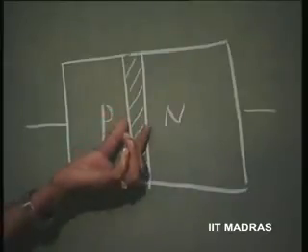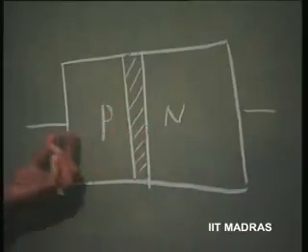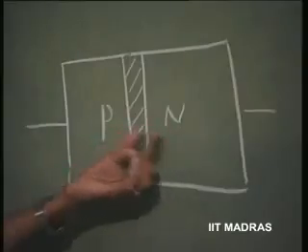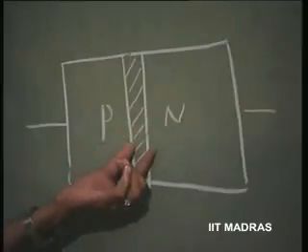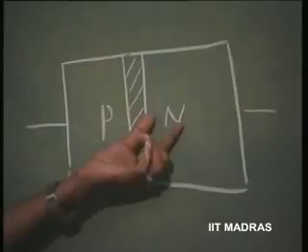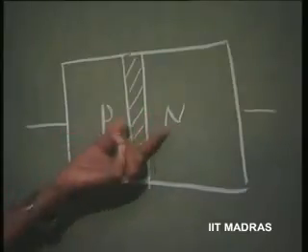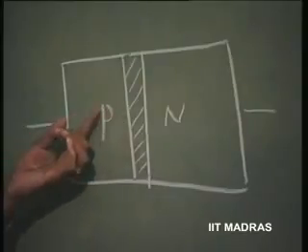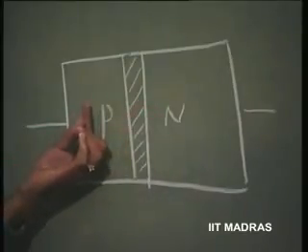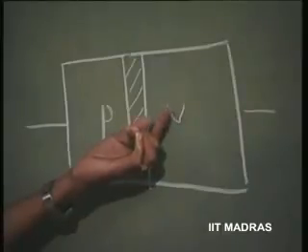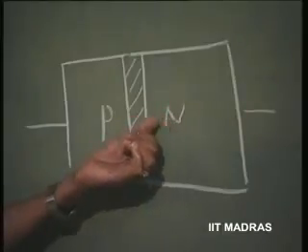Now, this particular junction is still permitting the minority carriers from here to easily go to this, because this potential hill which is an obstruction for the majority carriers is a sort of an aid for them to flow freely. So, there is a field here which will help these minority carriers from moving from here to here, and the minority carriers from moving from here to here.